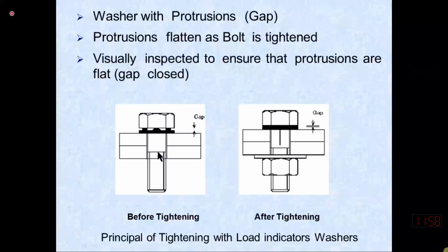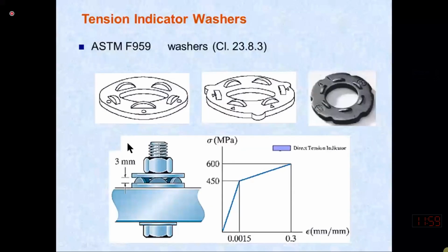These are truss connections with bolts. This is the bottom part, we have 3 bolts. This is the diagonal, we are connecting this with the gusset plate with 2 fasteners, and this vertical member with 3 fasteners. So we need to compute the number of fasteners required to transfer the forces from one member to the gusset plate and vice versa.